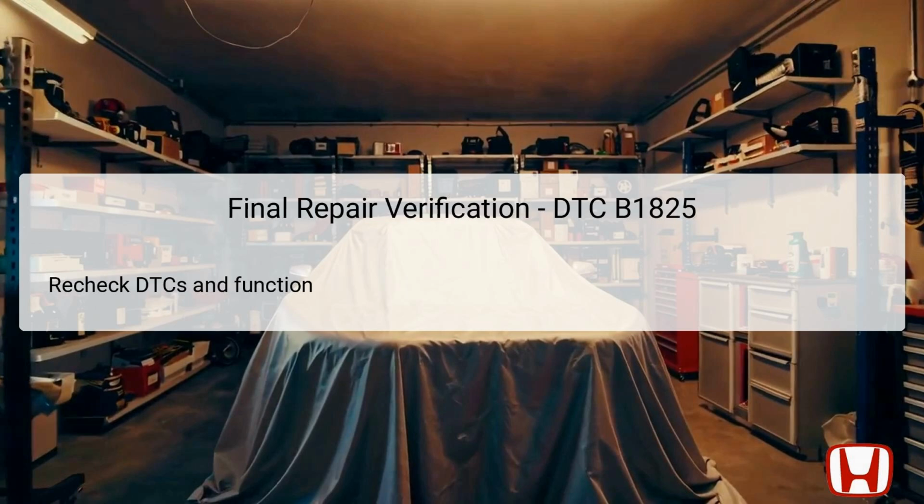After completing all necessary repairs related to DTC B1825, it's crucial to conduct final verification through extensive testing. Recheck the HDS to ensure that the previous DTC is no longer displayed. Additionally, operate the power seat several times to confirm smooth and accurate movement in response to switch inputs. This step assures that all connections and components are functioning well together, presenting a complete and efficient power seat operation.